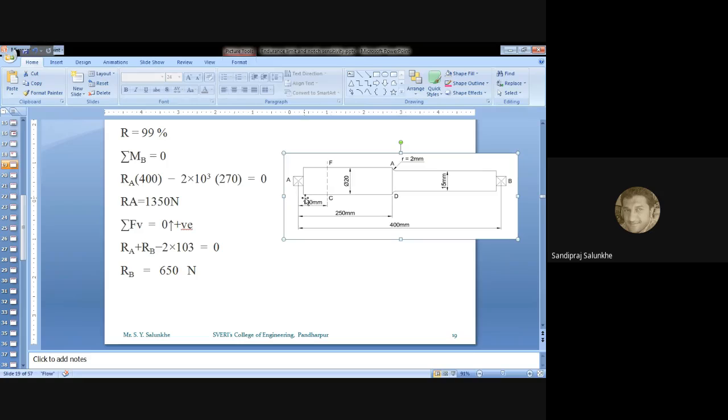As this shaft is not moving up and down, it is well supported at points A and B. It is rotating, but bending is not responsible for rotating. That's why we take the summation of all bending moments at point B equal to 0. So how can we calculate this bending moment at point B?